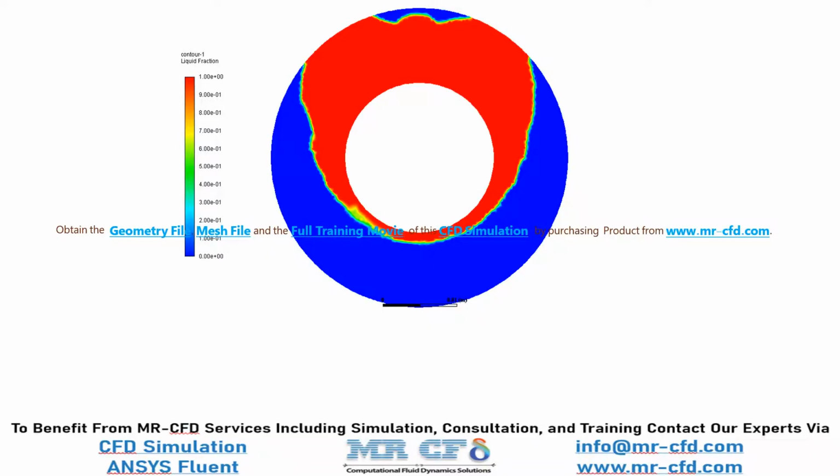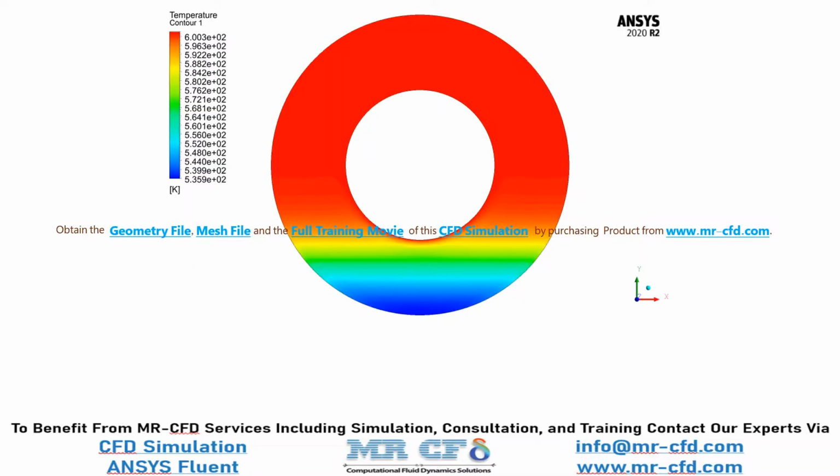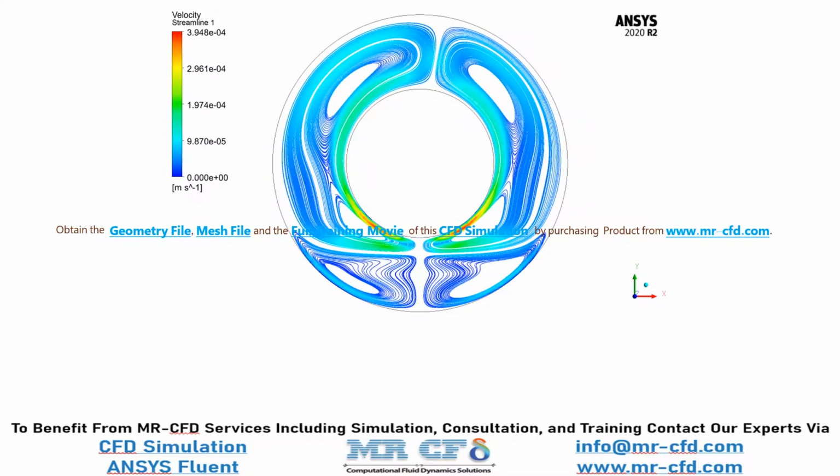Now, in this contour, you can easily see the changes of the liquid fraction of the PCM inside our computational domain. And in this slide, you can see the temperature changes inside our computational domain at the end of our simulation process. Now, in this slide, you can easily see the streamlines inside our computational domain, and you can easily see the role of natural convection in the motion of our streamlines.